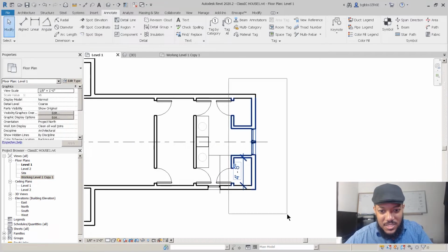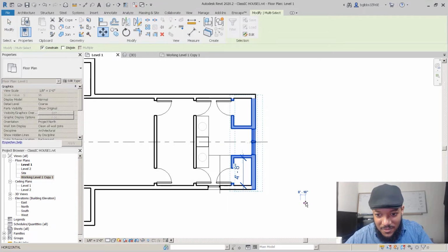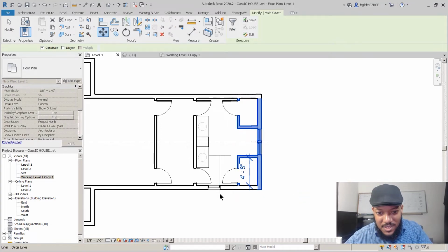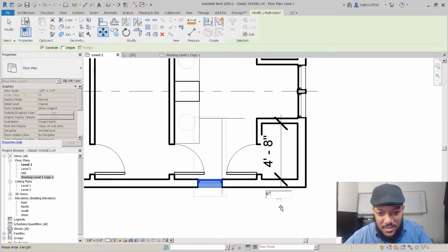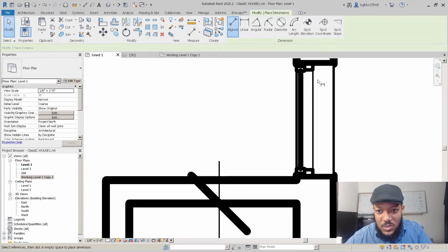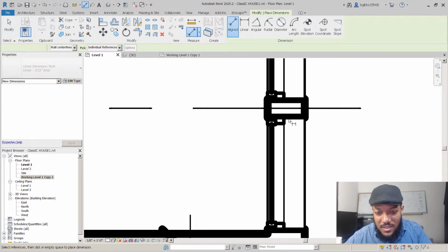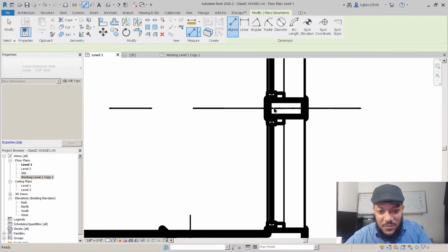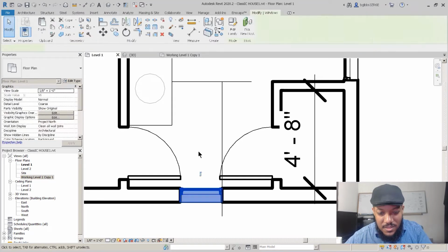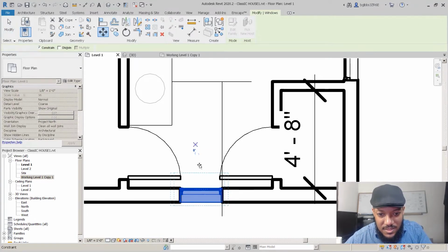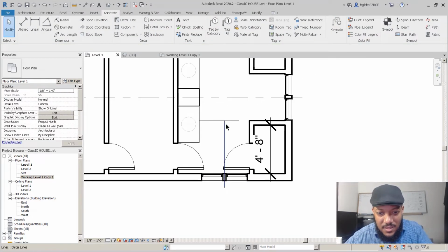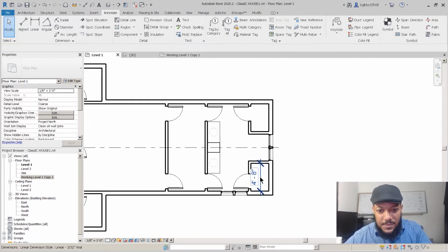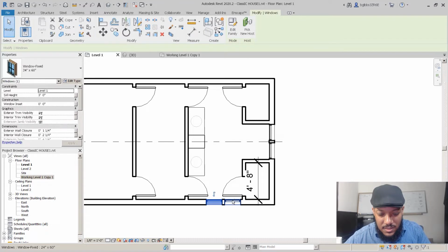Because we want to be a little more design centric, we'll go ahead and move this out 1 more foot so we have enough space for our window design. And that means we'd be moving this 6 inches to keep it centered. And we're going to measure that distance we have in between these 2 windows. That's 4 inches right here. So we'll do this 2 inch. And we copy that there.